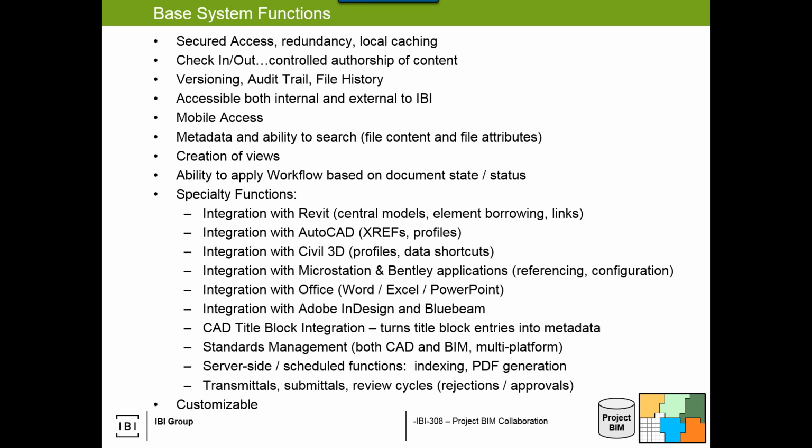But these specialty functions I want to touch on, we'll talk about Revit integration on the next slide. It integrates with AutoCAD, so XREFs and profiles, and handles the Civil 3D data shortcut project well. What we saw in our Viva project, if it swells too big, it may pose as a burden because it's trying to bring down too much content to the user's machine, so they ended up splitting it for better management of it, and they're rocking.